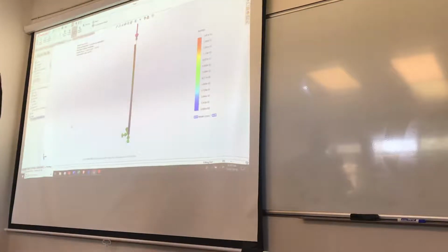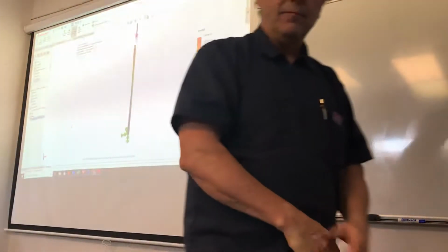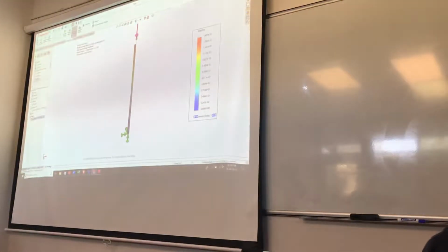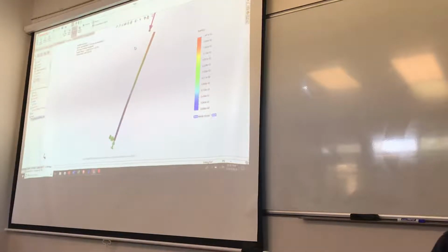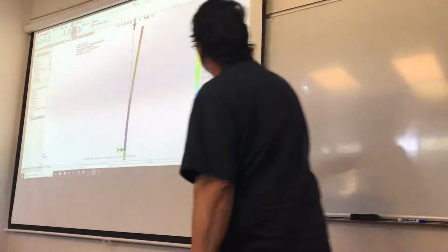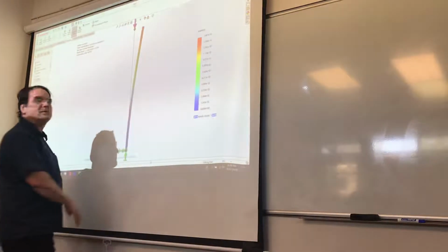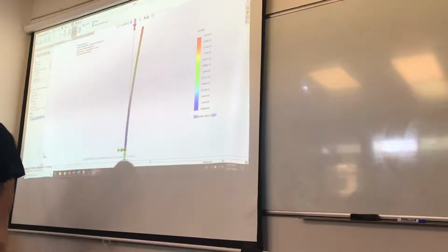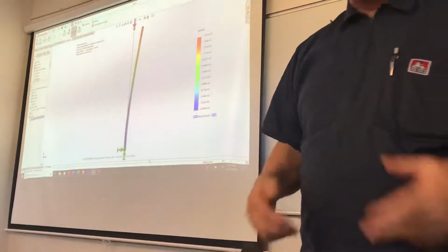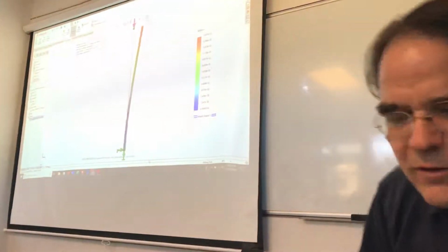So that's buckling. Now, what are these mode shape things? Right? What are these mode shape things? Well, it winds up, of course, that if we sort of spin this thing around and look at it, it's bending. And then let me see if I can play with that thing. It's actually deforming out, right? And this is making what's known as a mode shape. It's a curved shape that it will get in the way it is failing, a mode of failure.